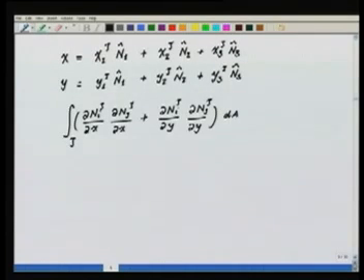We would like to convert it to an integral over the master element. So from the physical, I come to the master, where I have the integral over the master element tau hat of this integrand, converted into an expression in terms of psi eta, into now the area in the physical element has to be mapped to the area in the master element. So that will be in terms of something called the Jacobian into dA hat.